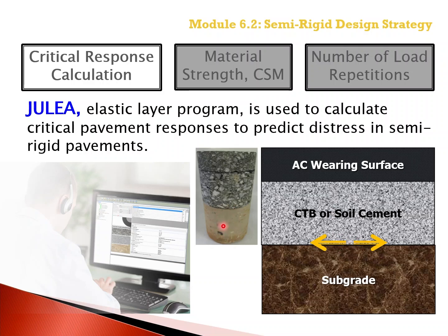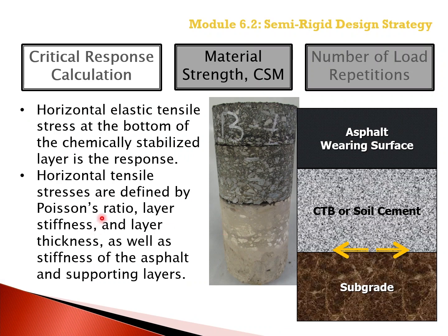Again, only if that layer has flexural strength and can resist tensile stresses. So horizontal elastic tensile stress at the bottom of the chemically stabilized layer is the critical layer response, which is used to predict the fatigue cracking of the chemically stabilized layer.